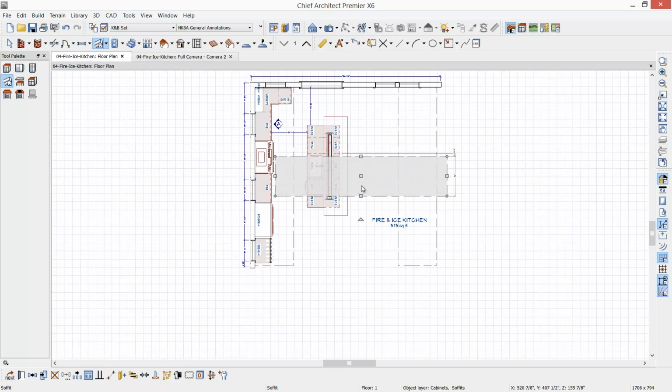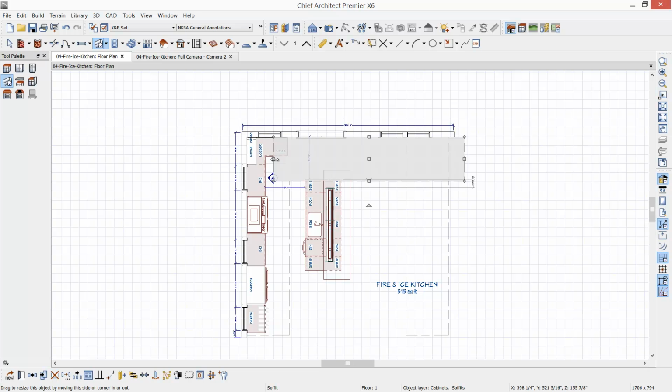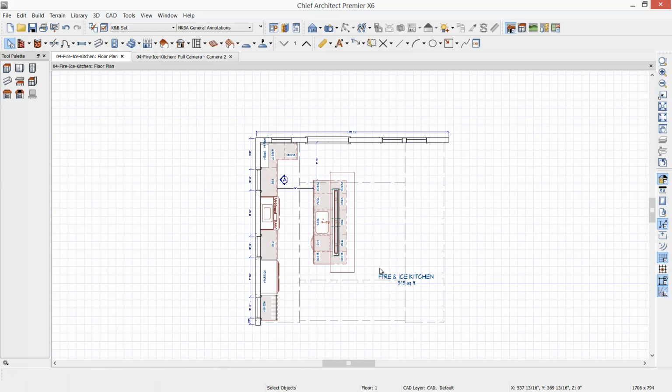It's a little faster than creating yet another soffit. Bump it in, and then I'll snap it to the edge of the two soffits. There we go. And then again, copy and reflect about the center of the room. Roughly I have the soffit positions; I'll make some final adjustments a little later.